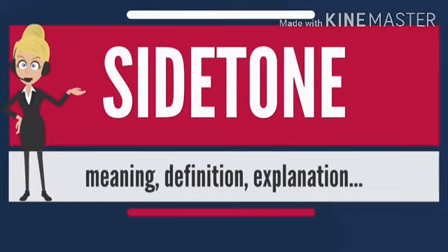Side tone in 19th century telephones varied until the carbon transmitter was used, which produced a distinct side tone that discouraged speaking loudly enough, and occasionally so loud as to cause the instrument to produce uncontrolled oscillations, resulting in howling audio effects. Side tone is disabled when phones of any kind are running in speakerphone mode, due to perpetual and almost immediate feedback. Anti-side tone circuitry incorporating the principle of the hybrid coil brought side tone under control in the early 20th century, leaving enough feedback signal to assure the user that the phone is really working, and allowing the use of a unitized telephone handset.